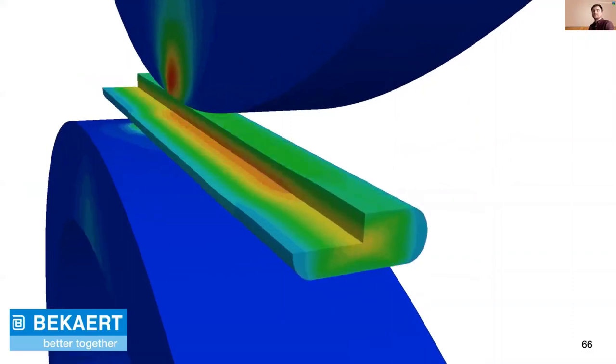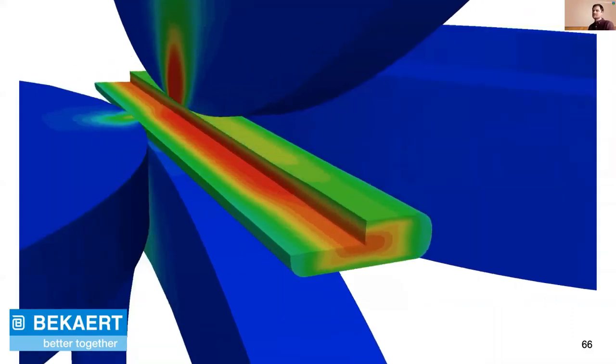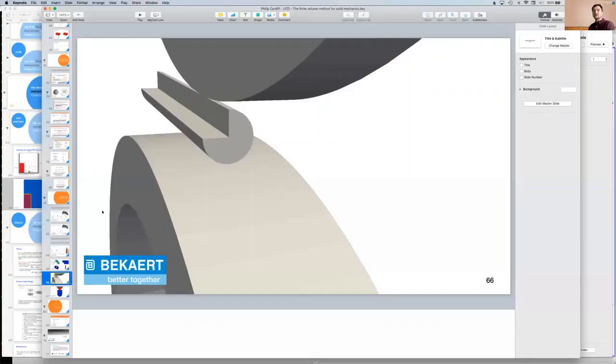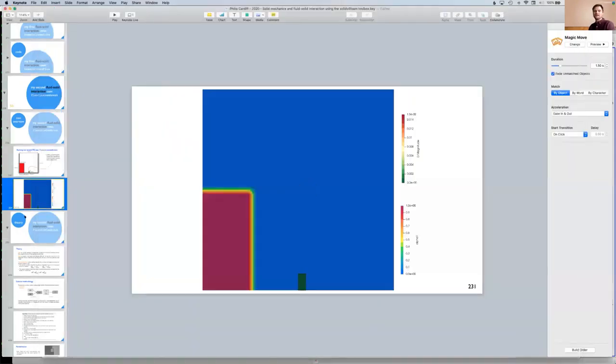And we use it there to really squash pieces of metal. This is one simple example because I'm not allowed to show any of the cool, nice videos, which is really plain. But the cells really get squashed in this, so the deformation really is large. For this specific solver, a lot of the general code gets shared back into Solids4foam. The specific solver for this isn't, but the general methods in Solids4foam are there, so you can solve these style of problems.